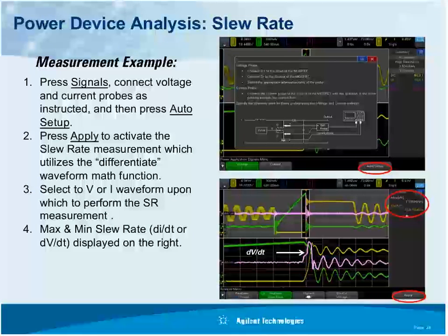This one right here. So here we can see the voltage waveform ramping up and the current waveform ramping down. I'm trying to see what the time base is. It says 72 nanoseconds per division. So there's not a lot of time between the voltage going up and the current coming down. Just a few nanoseconds of skew will significantly change your power loss measurements.